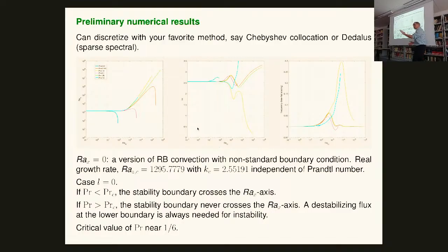So then what you do is you increase your horizontal Rayleigh number, and you say what happens. And what you find is this is the marginal stability curve. So over here I'm stable, here I'm unstable. I increase my horizontal number. Nothing happens, and suddenly it crashes down. I stopped here, but it goes like that, completely vertical.